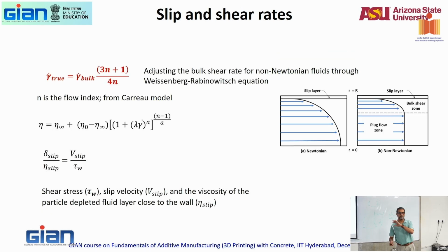So lots of calculations. Again, we have one full paper published on the entire set of calculations, right from how you characterize it from all the viscosities and all of that. Here for viscosities, because we needed more parameters, we did not use a standard rheology equation like your Bingham model or Herschel-Bulkley. We actually used what's called a Carreau model, which is a viscosity model.